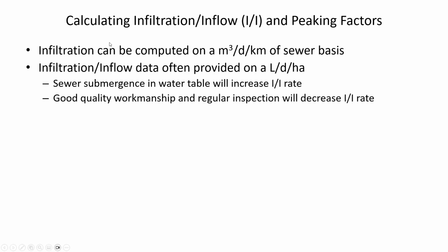So infiltration and inflow, there are different ways that you can account for it. Sometimes you'd have it based on the length of the sewer. So here this is saying it can be computed on the basis of cubic meters per day per kilometer of sewer line.